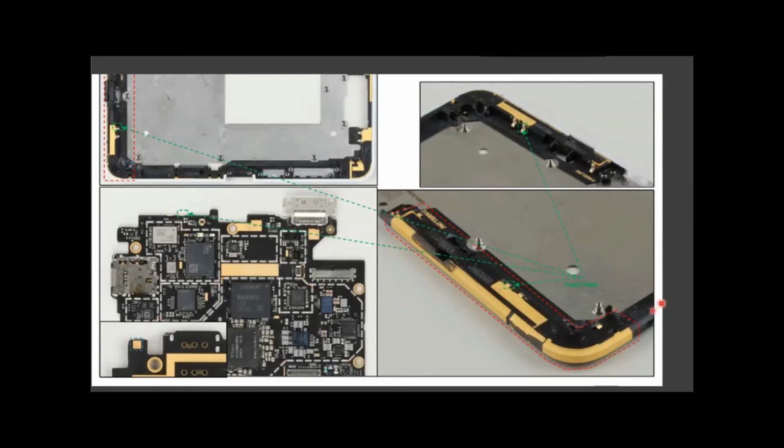It's a nice process where this plastic has a special chemical in it that's activated by a laser beam. So we put this blank plastic into the machine, and we laser this pattern on the plastic, which activates the chemical inside. Then we dip the plastic into a bath of copper ions, and the copper ions adhere to the activated parts of the plastic, and that's how you get this antenna pattern.